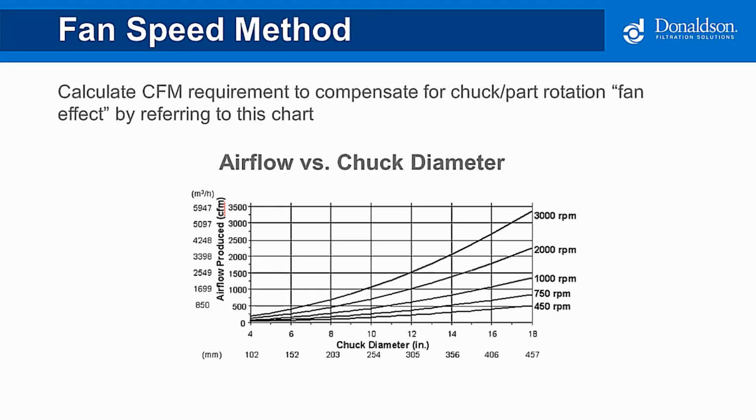If the RPM you require is not on this chart, you can find the calculations in the industrial ventilation manual, which we'll talk about a little bit later. But typically, most wet machining applications that are enclosureless are not going to operate at speeds higher than 3,500 RPM. Now, if you do have that case where you are operating over 3,500 RPMs and you don't have an enclosure, I would strongly recommend that you enclose the machine for best performance and overall safety.